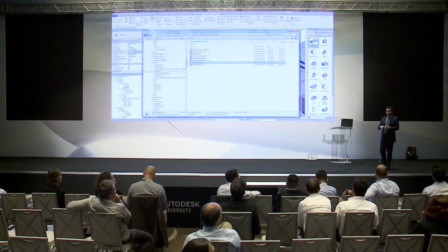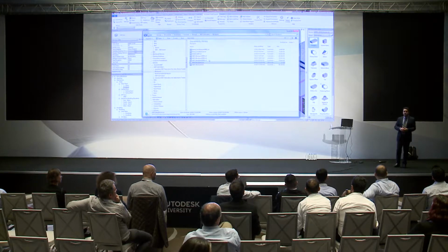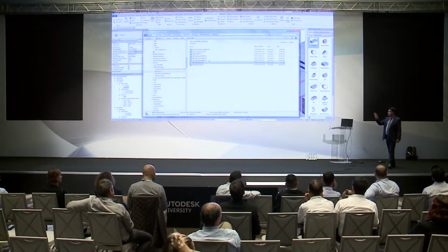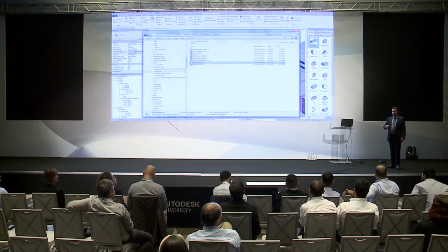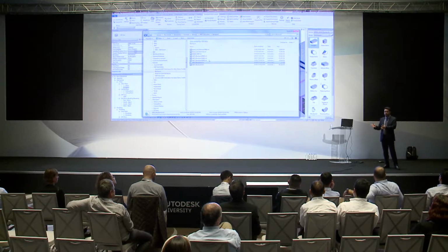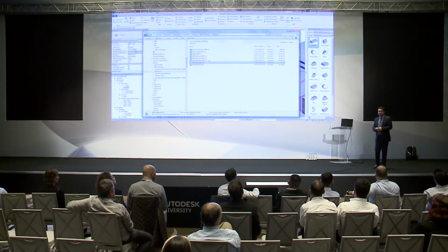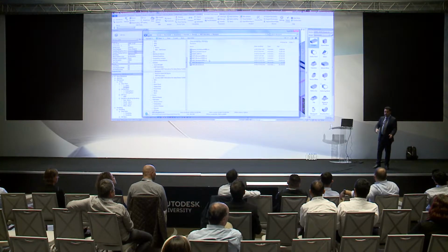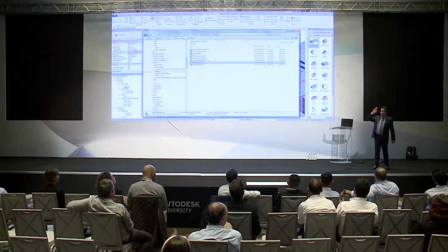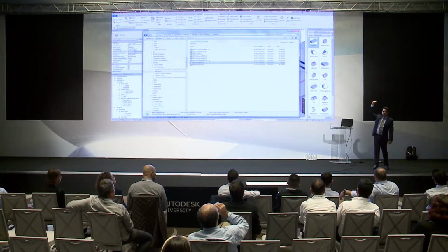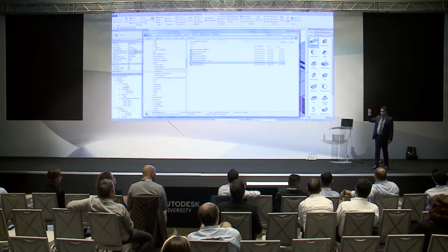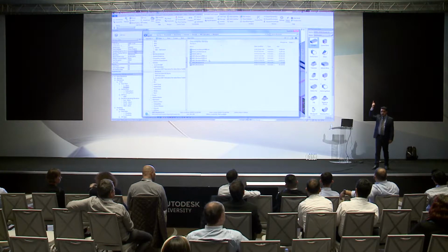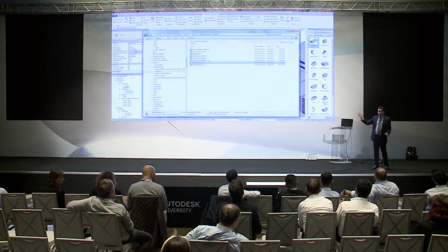Absolutely, that's a human thing. And it reminded me of something, maybe I can show you later on. There's a new robot, as you've seen in the morning as well. What it does is it takes those points which I just exported, and it moves around the site. It shoots a laser, and it goes to that particular floor slab, and it knows the coordinates as per your model, and it will drill a hole for that hanger one by one, without anybody doing anything.